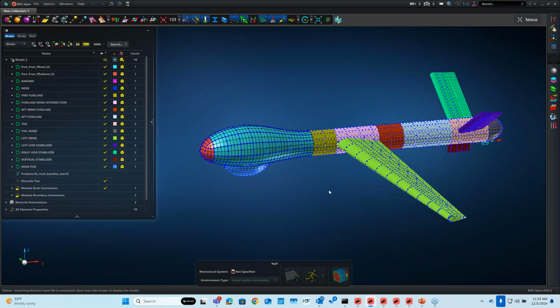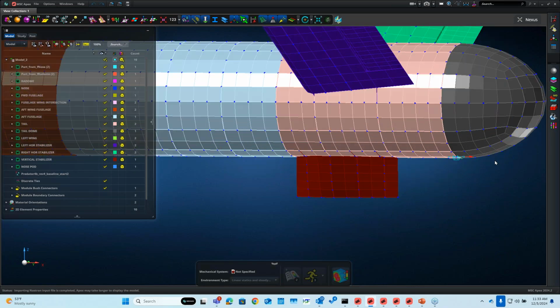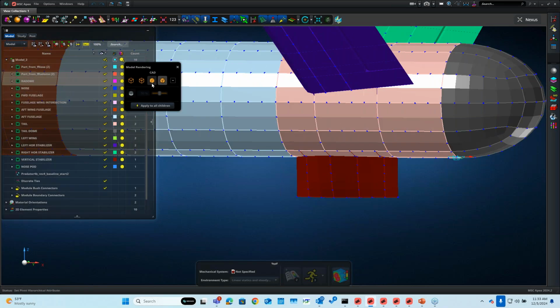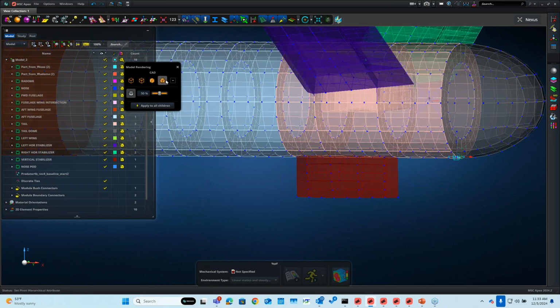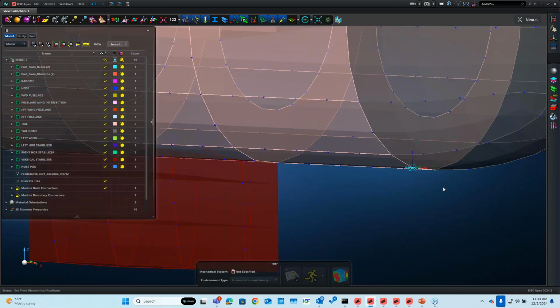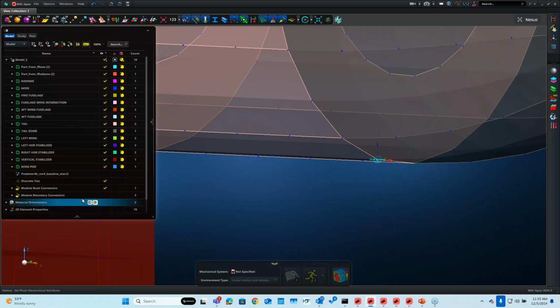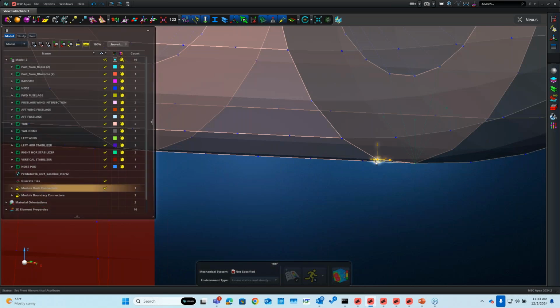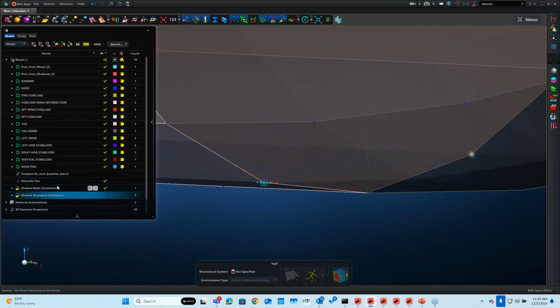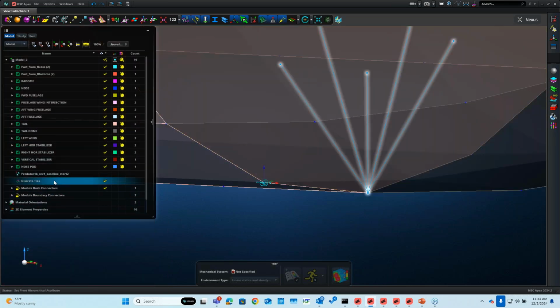I want to talk just a minute about additional connections, all right? So let me go to a transparent view. So we'll go transparent here. So we've talked about automatic, but automatic is not the only option for connections. So here, I've actually got a bushing that is doing a node-to-node connection because maybe I want a particular stiffness between my connection. I don't want it to be explicitly node-to-node. And I've also got like an RBE2.